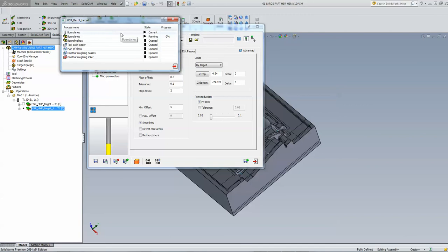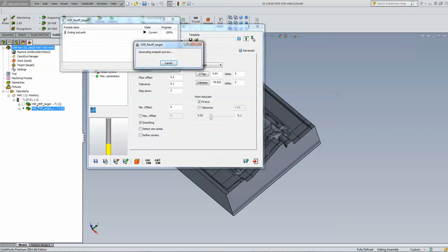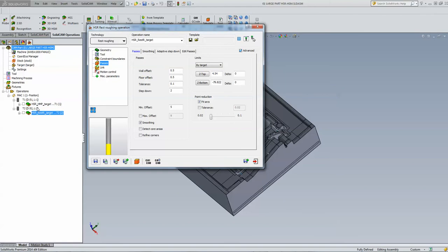Note, it's going immediately into the calculation of the toolpath itself without having to go into the option of updating the stock. If you remember from my previous webinar, there's a setting for updated stock that's special for HSR and HSM, and I'll show that for you in a moment, where if all the operations are HSR and HSM, you can use that option to make your calculation go a lot quicker by just skipping. It does not need to do that updated stock inside the calculation.